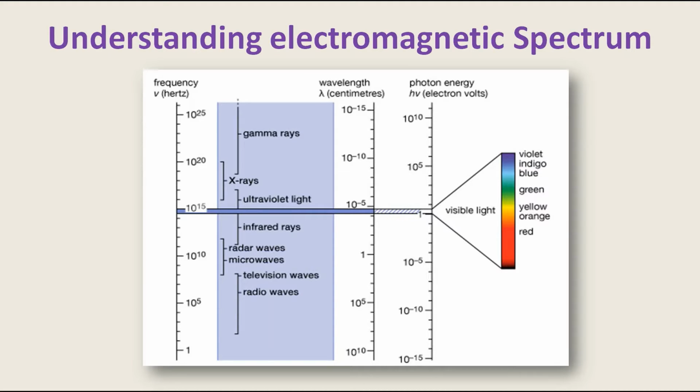The range of wavelength for equipment having temperature above 250 degrees centigrade lies between 0.72 microns to 10 microns. Therefore, this radiation is focused onto a detector. This detector acts like a black body so as to absorb the entire thermal radiation incident on it. The increase in temperature of the detector will be a measure of the temperature of the hot body.